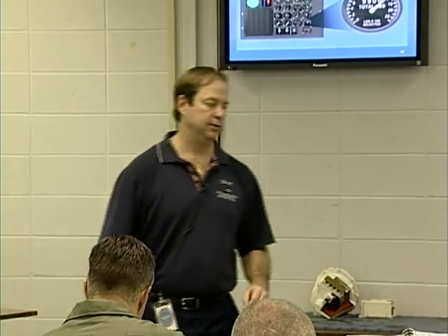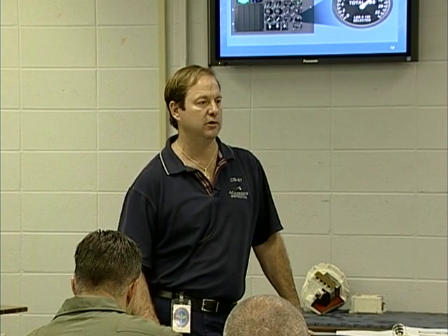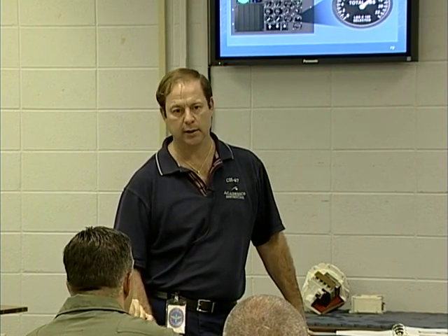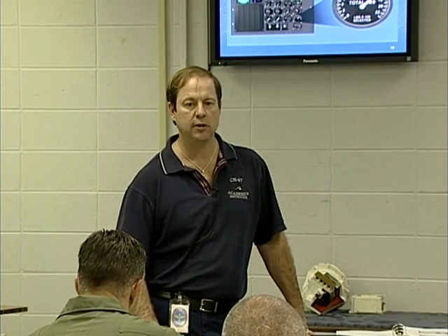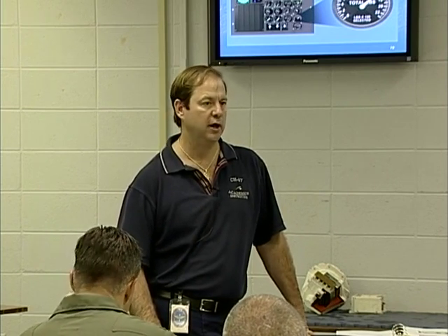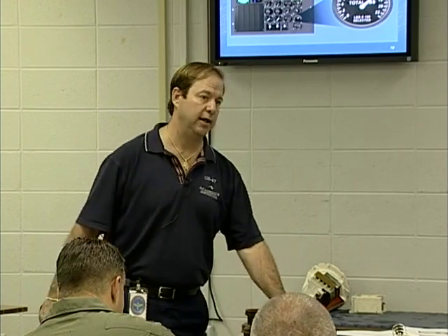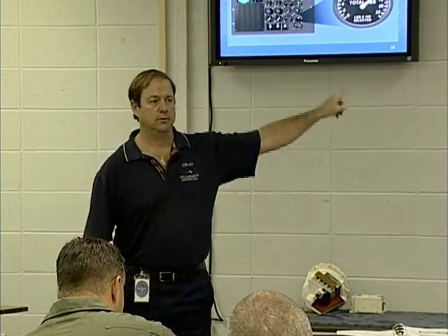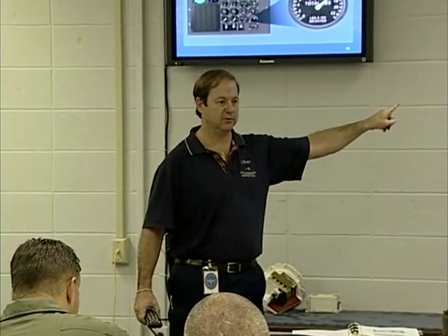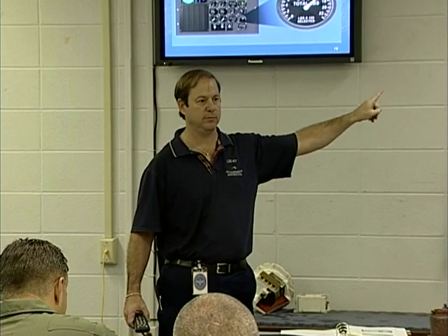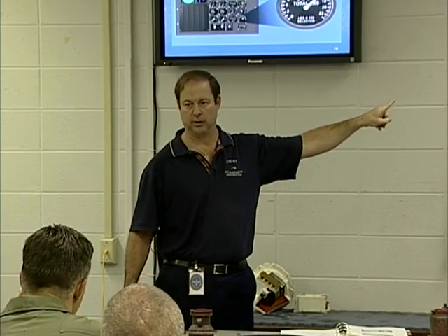I'll go one step farther. I'm usually not a negative person. But if I was going to tell you anything negative about the CH-47, the fuel totalizing, the fuel quantity indicating system, in my opinion, just stinks. When you need it the most, it becomes the most unreliable. When you get into that low level, when those lights are illuminated, you never know what that indicating system is going to do. So if I had to point out a negative, this would be it. My word to the wise: if you have an opportunity to take on fuel, take on fuel. But you've been told that your whole Army aviation career.